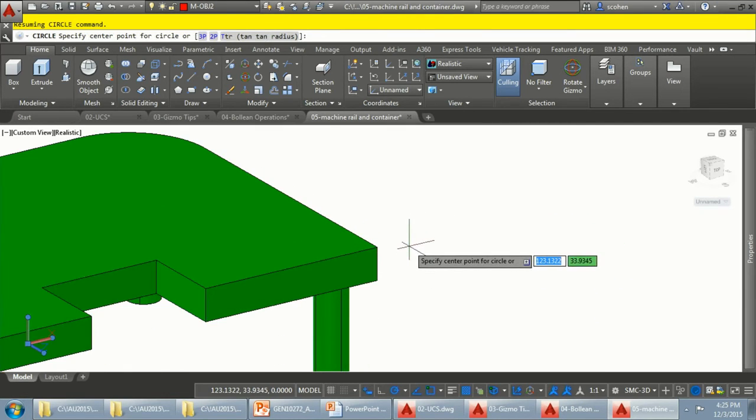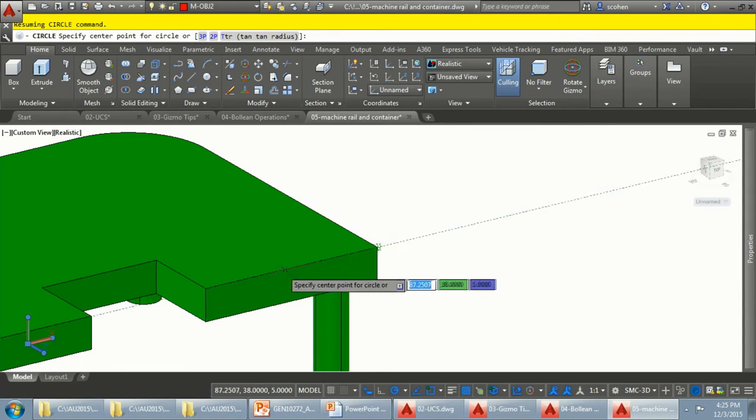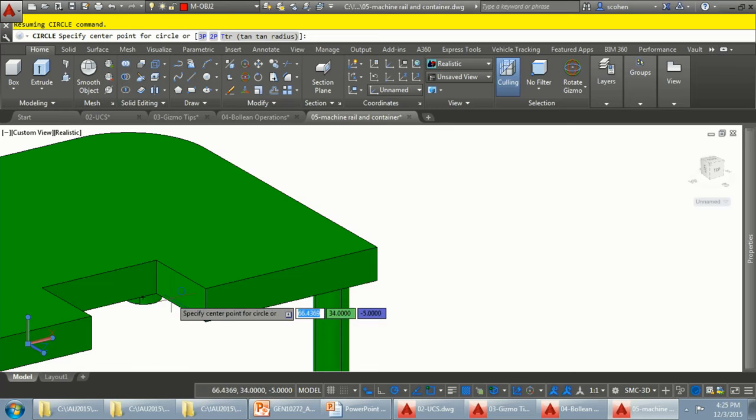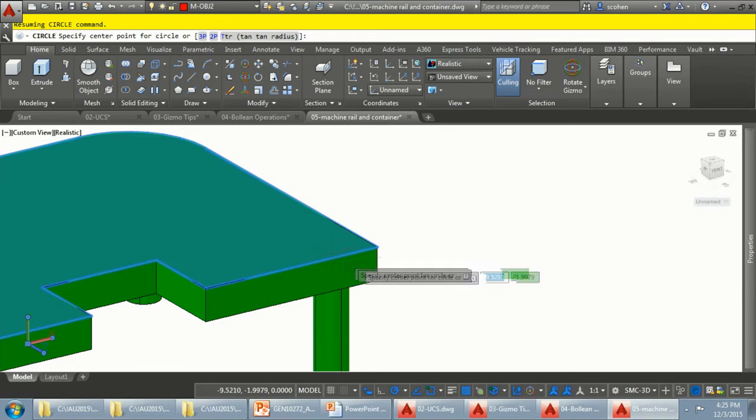Now my radius is going to be 5, so I'm going to acquire this point. Again, using O tracking, move to the left here, of course, not snapping. Oops, did I? Okay, so here's a little bug. Actually, not a bug, but well, I think it's a bug, but this is as designed. So notice how I acquire, and I'm trying to get the extension, but it keeps going away.